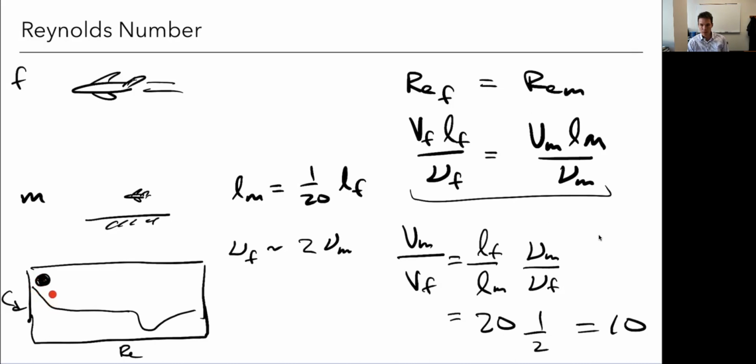There are very few engineering applications where that's even applicable, right? A lot of our stuff is here, and then big airplanes, fast things are kind of here, where things don't change very fast. Reynolds number is the one exception generally of all the non-dimensional numbers you'll see. Most are of order 1, right? Lift coefficient, Mach number, pressure coefficients. Most things are order 1. Drag is smaller, but most things don't vary across huge ranges. But Reynolds number does, right? For a full-scale airplane or a big wind turbine, these are in the millions, tens of millions. Even little small things are hundreds of thousands, right? Like a little small RC plane.